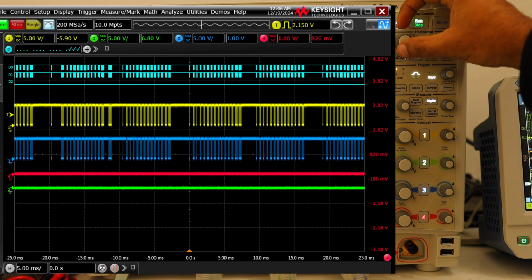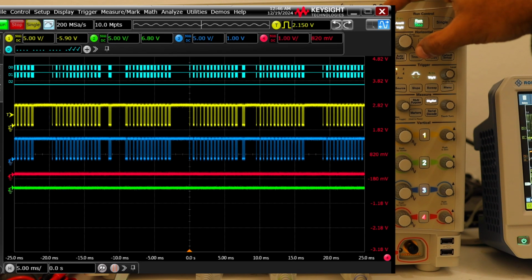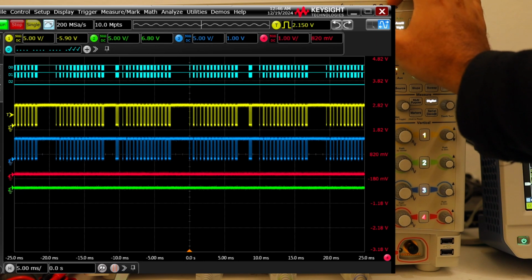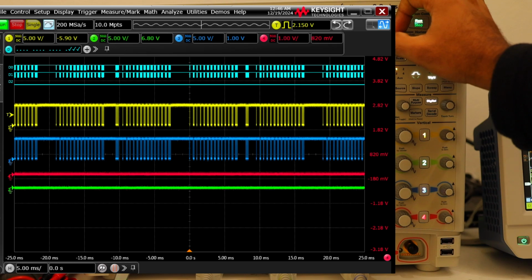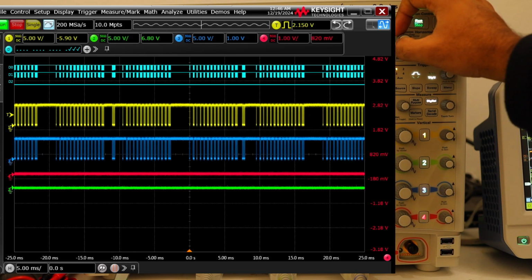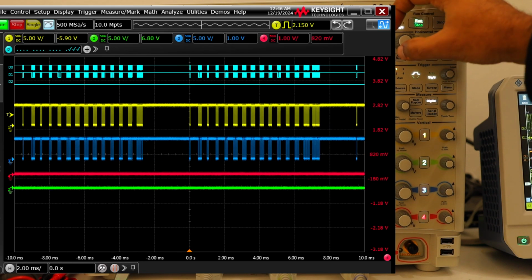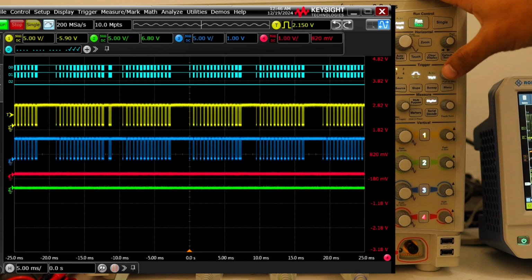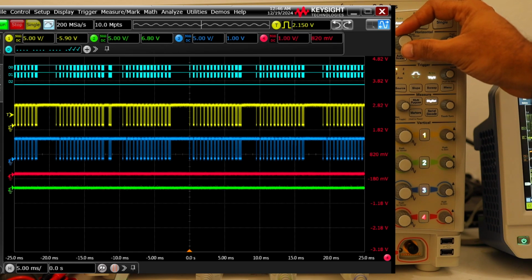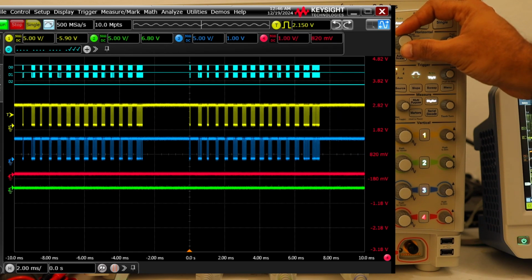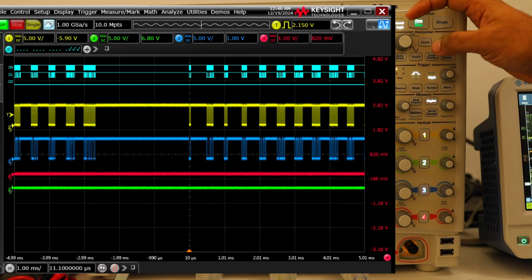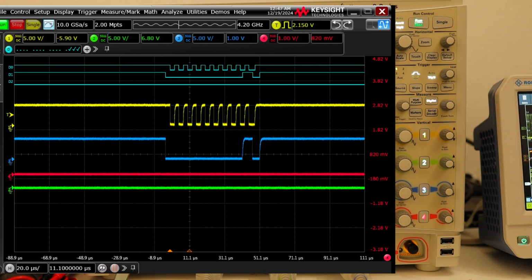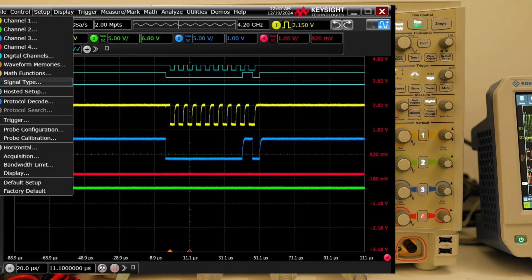Same stuff, some packets arrive and disappear. So this is the packet which you saw on the RTB2004, which was displayed at 547A7B, and on the other oscilloscope it was displayed at address 18, because they are most likely two different packets, and we can definitely trigger on both of the packets if needed. But right now we are only concerned about the packet which we're seeing. And let's set up a decode. First of all, we set up a decode, then we will see the rest of the things. Let's zoom in a bit, and I'll show you. Setup.